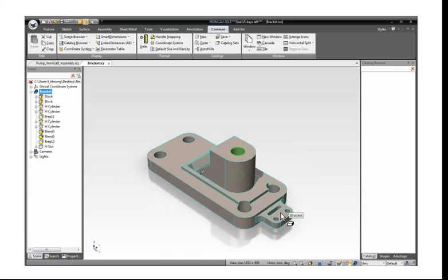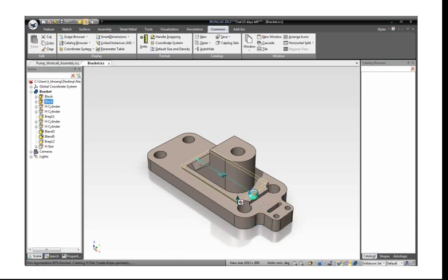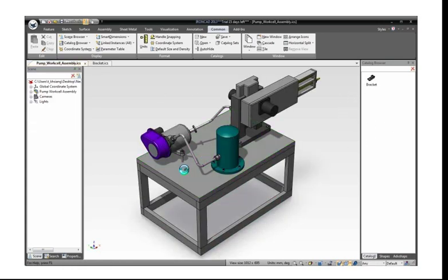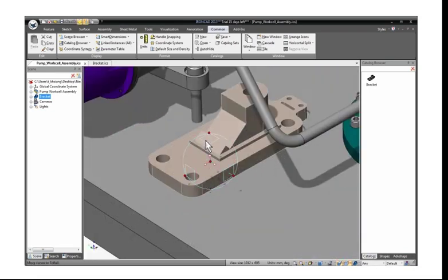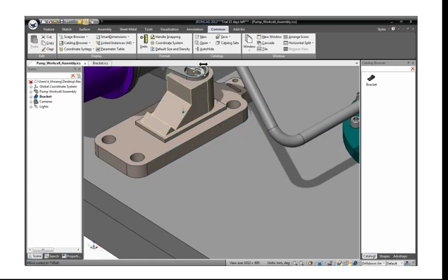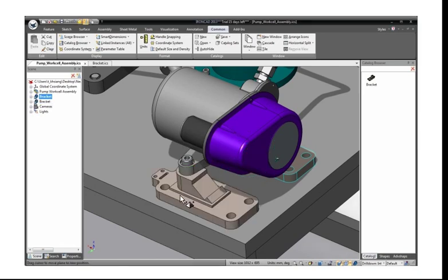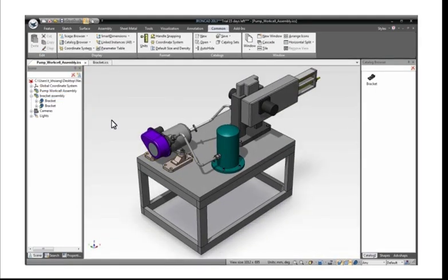The unaffected features can then be used by their initial definition for future modifications. The resulting part can be dragged and dropped into a catalog and reused in any other design. Here we are using the triball to position the updated design and then using in-place direct modification handles to modify the supporting face to match the height of the supported object. Next, we use the triball to very quickly create a new linked instance to support the other side. This action of using an existing object and dynamically modifying it can be done not only with parts created in IronCAD, but also any imported part.